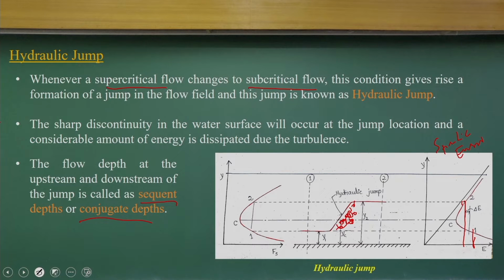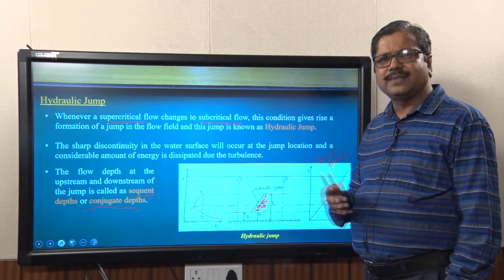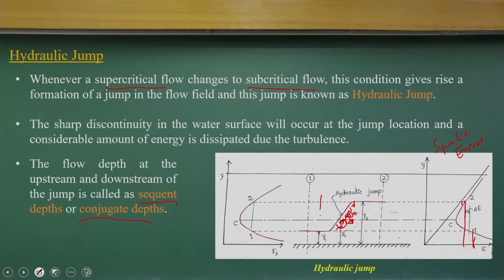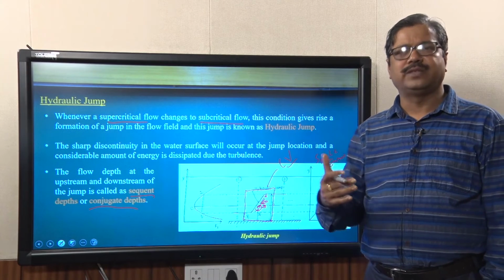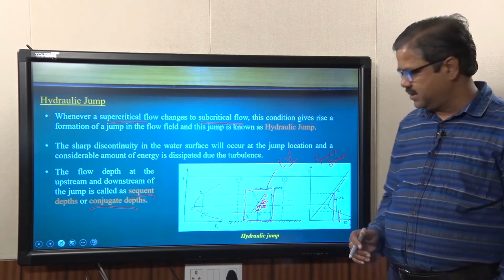I look at these hydraulic jumps as part of the specific force concept. When you consider the specific force concept, I can use a control volume like this. When I use this control volume, we look at what forces are acting on the control surface.